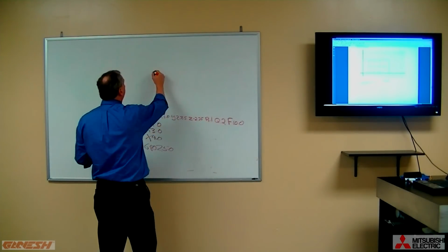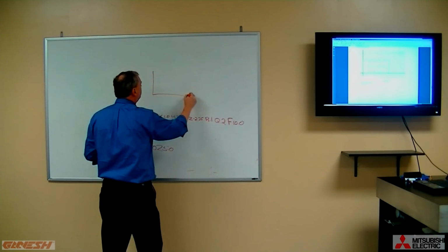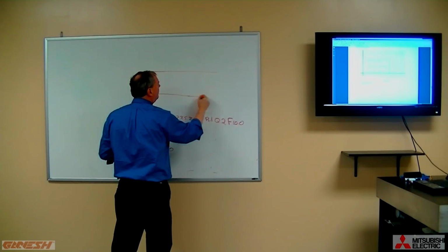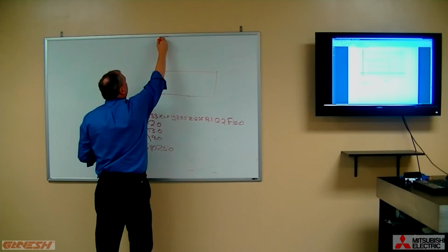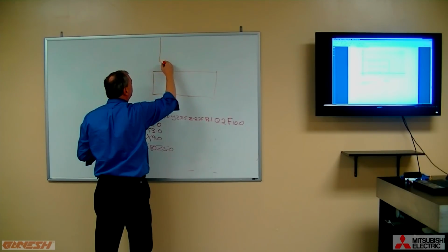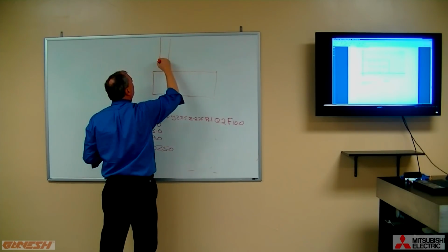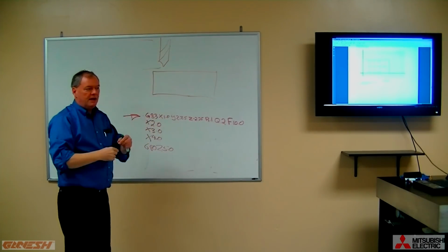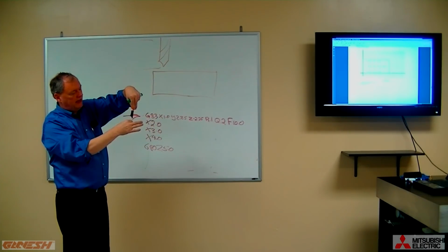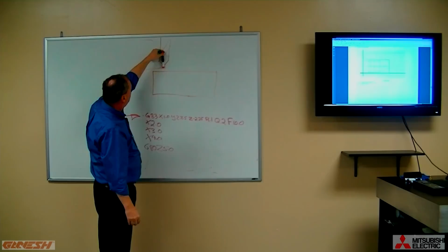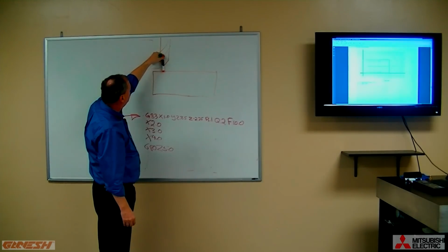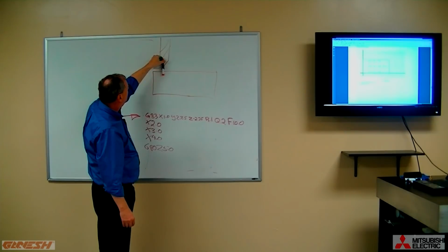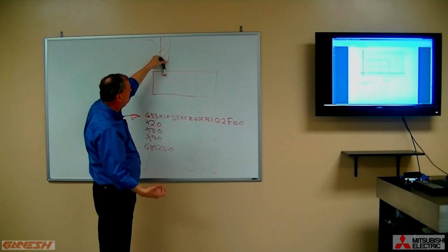Because if we're going to drill a hole in a solid piece of metal, you have to realize that our drill is sticking out some amount from a chuck. This amount that the drill is sticking out makes it kind of prone to wobble and wander. So if you start pushing this down into a material, it's going to start drifting around like this until it grabs metal and then starts cutting.